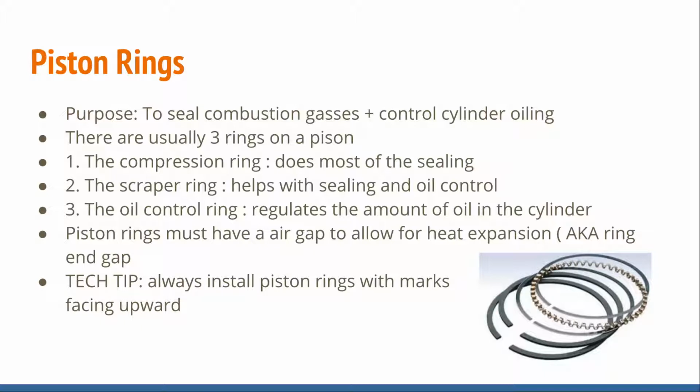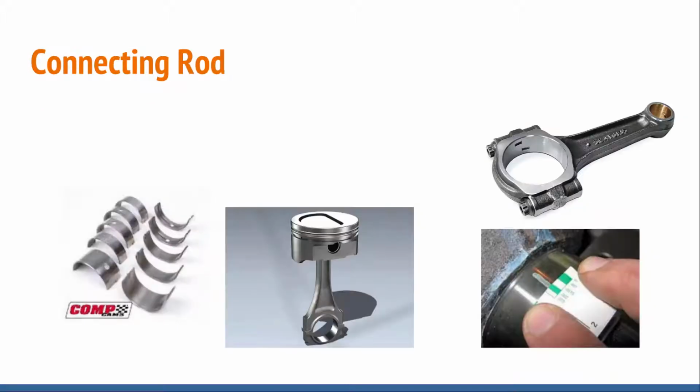Here's a little tech tip for you. Always install piston rings with the marks facing upward. And what I mean by that is, if you look real closely, sometimes on the very top of the piston ring, it's going to have some part numbers, some letters, whatever. It's going to have some sort of marks for you. Those marks always need to face upward. So make a note of that.